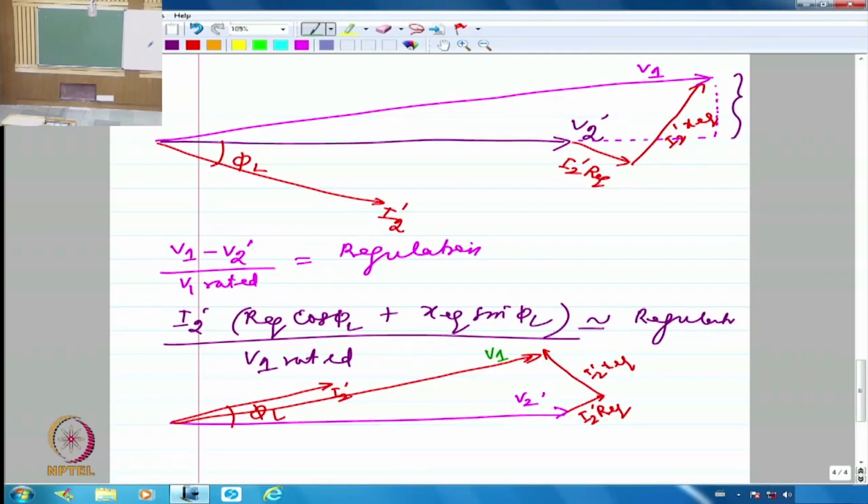If it is a 1:1 transformer, I am talking about a 1:1 transformer, you can say that capacitive loads normally increase the voltage that comes out on the secondary side. This happens because what is inherently within the transformer is inductive in nature, so the capacitance kind of nullifies it. The impedance of the transformer happens to be inductive in nature.